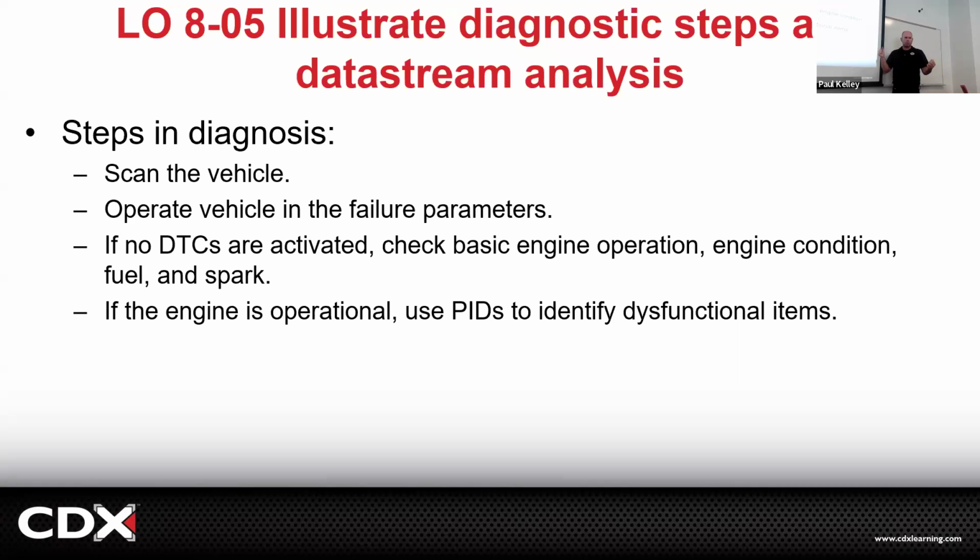So sometimes you got all these different potential tests you could do, but right here, you only really need to operate it in the failure parameters if it's not doing it. If it's already broken and you can tell it's acting up, now I'm pulling that sucker straight in and I'm going to figure it out right then and there. I don't need to go drive it a lot because it's misfiring right now, like his was, and I saw it. There was white smoke coming out the tailpipe, and there were definitely clues, but he confirmed it, and I'll have it on video too.